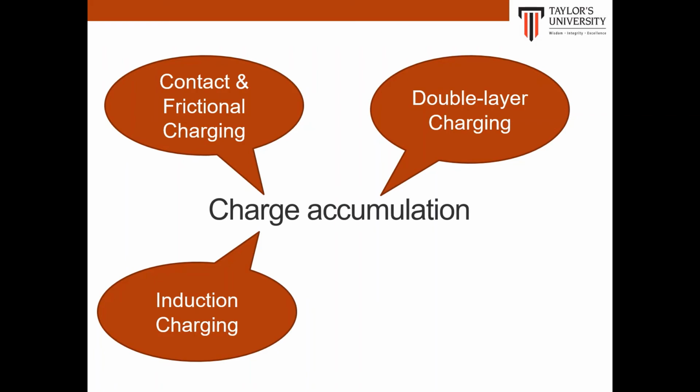Electrons in the person's body, the head, the shoulders, or arm, migrate towards the positive charge of the vessel, thus accumulating an equal quantity of positive charge on the opposite side of the body. This leaves the lower part of the body positively charged by induction. When a metal object is touched, there will be a transfer of electrons, creating a static spark.